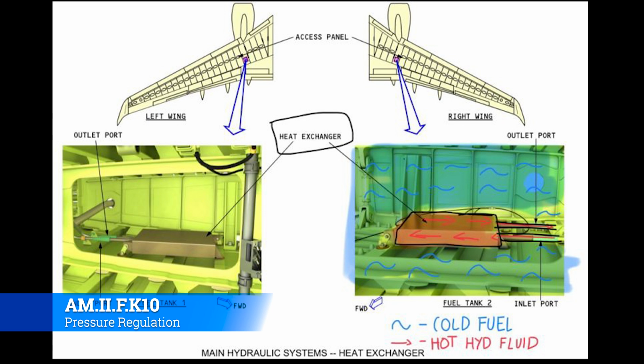But essentially, hot hydraulic fluid comes into the heat exchanger inside the fuel tank on either side, and then it gets routed through the fuel so the fuel can pull some of that heat away from that hydraulic fluid, drop it down so that way it goes back into the system nice and cool. Otherwise, you would have a serious problem with component failure and potential fires because that hydraulic fluid gets extremely hot, and you have to cool it down or else you'll suffer the consequences of that heat.